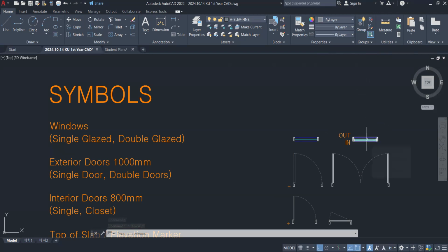So two pieces of glass in the window frame. There are even triple glazed windows that are more insulating than double glazed, but for this semester, we're just going to follow single or double. I've drawn in both because in the precedent study drawn in this CAD file, it's single glazed. The project is based on the S House by Sana, located in Japan. It's a very mild climate, so they only use single glazed windows.